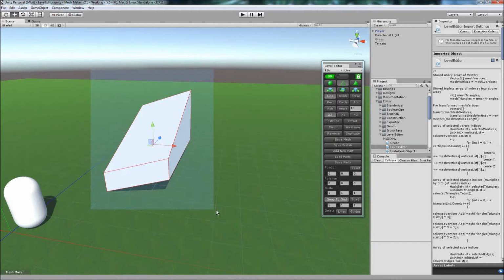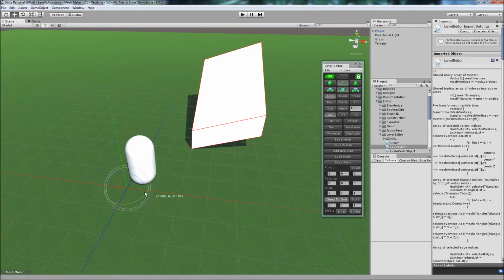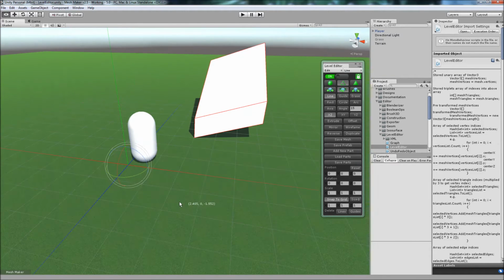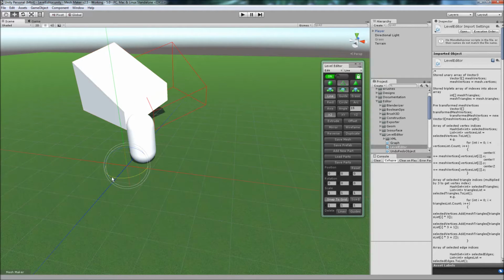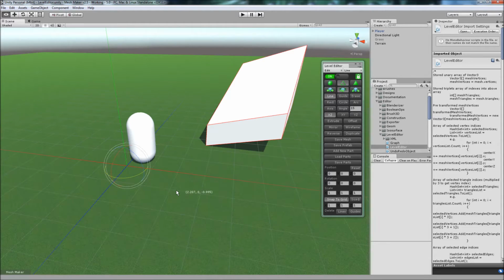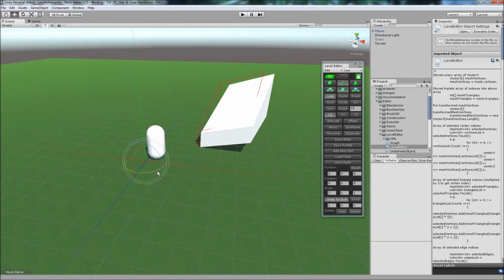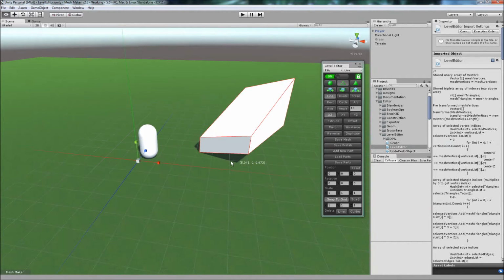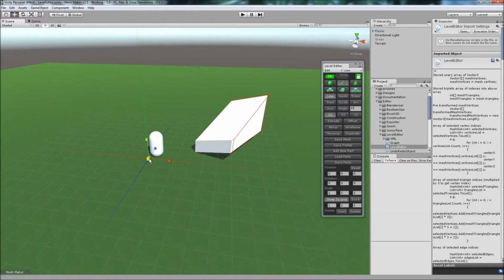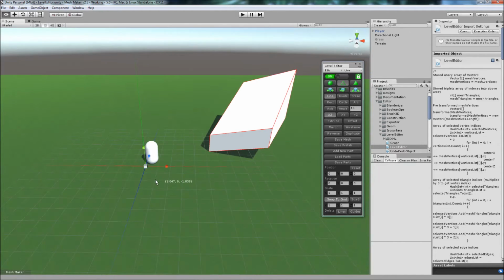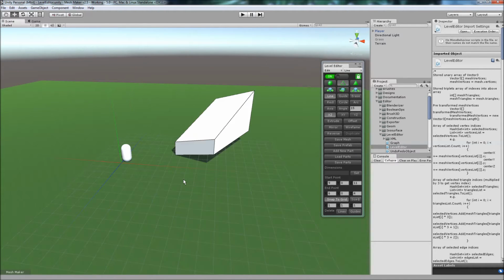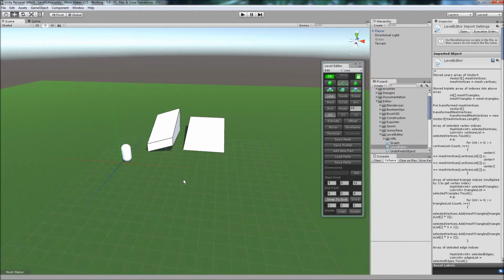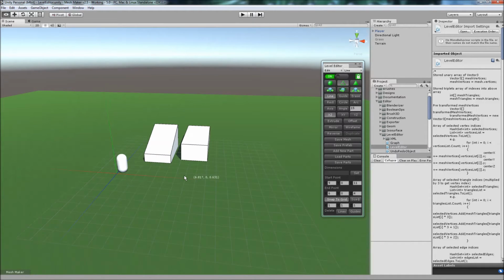And if I select all of the edges of this one here and we switch to rotate, you'll notice that the rotate tool has popped up here, and if I rotate the object, it will swing around this pivot point. And the same is true for the scale. It'll be relative to the pivot point here. If I expand all, we can change the size of it that way. And of course we can undo using the Ctrl-Z key.